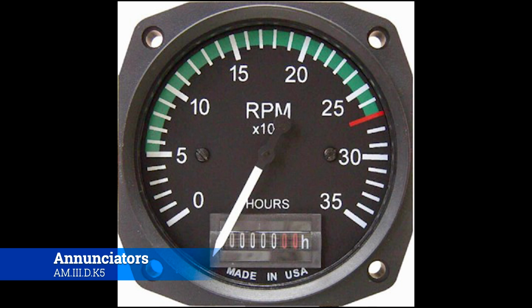What the RPM gauge is effectively going to tell us is how many revolutions per minute, in hundreds at least on this gauge, the engine is operating at. So if it's sitting at the 5 at the bottom of the green arc, it's only making 500 RPMs. Why is that important? Well, if the engine is set at a certain power setting, so you put it at 1,000 RPMs, then you can infer certain performance characteristics. You can infer certain fuel burn, all this other good stuff.